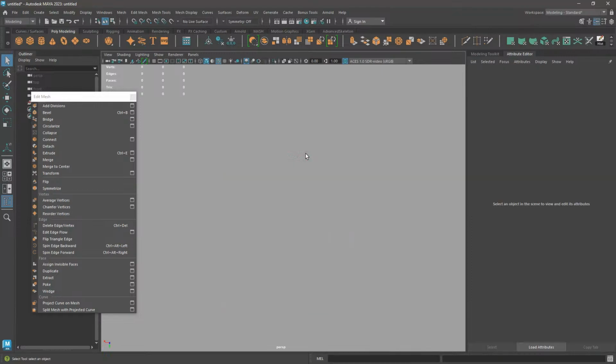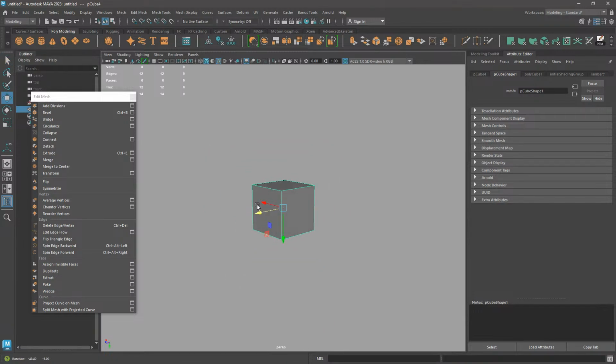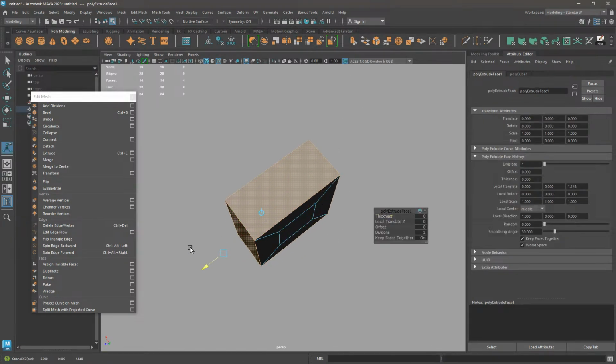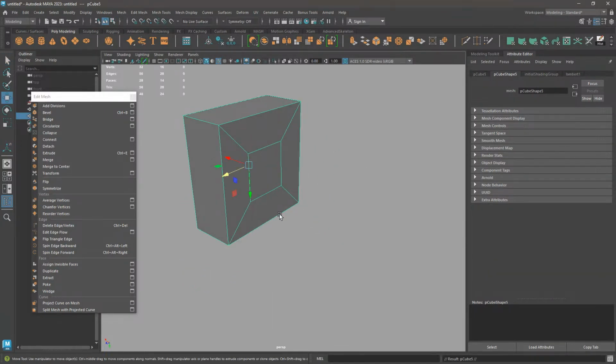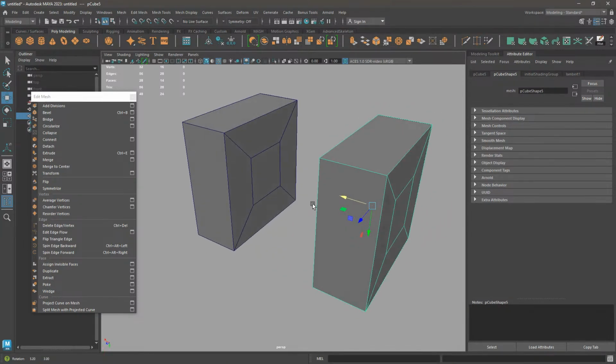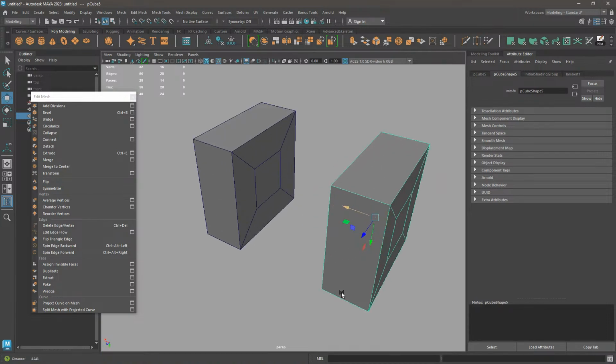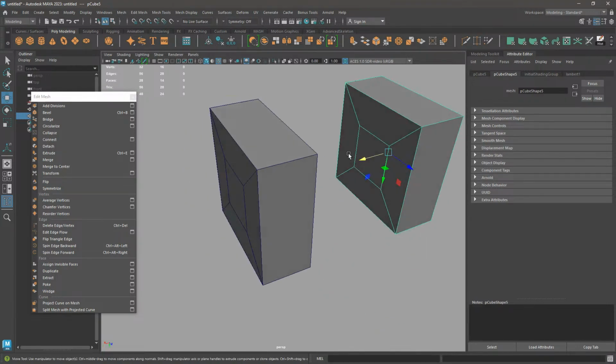Okay, so I'm going to delete this one. Now we tried the bevel. Now let's go to the bridge. Right now what I'm going to do is select only these sides of faces. I'm going to extrude and I get something like this. Then I'm going to press Control D and make another copy of this one. My goal is to connect a cylindrical pipe, maybe a cubical pipe, to this one, so these two are connected.